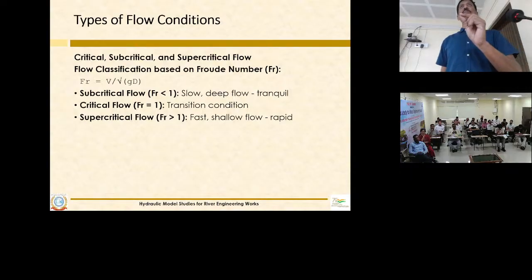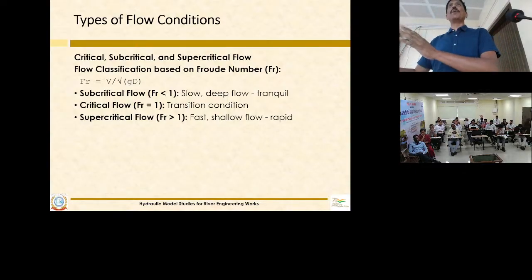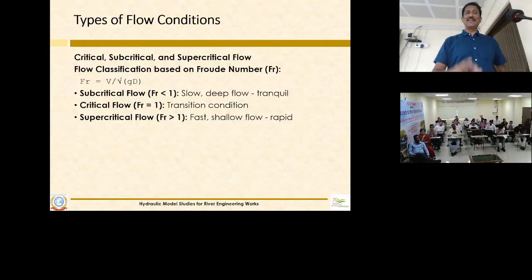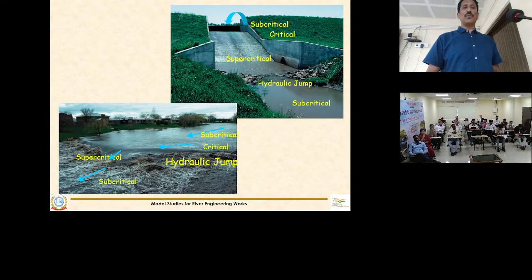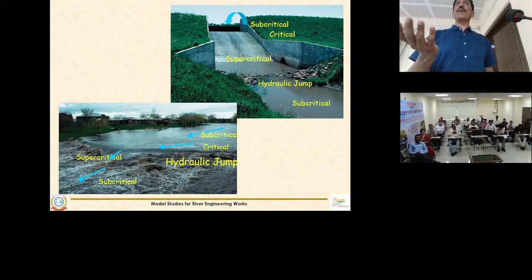But from the modeling perspective, you have to remember what the velocities and likely Froude number are. In the first initial calculation you do, you'll see the calculation table. Madam and sir will be showing you the output table. Just go through the Froude number you are achieving. If there are any changes, you have to rerun the scenario. So these are the flow conditions we have to see and then run our model. These are just examples of how flow changes over a short period of time.